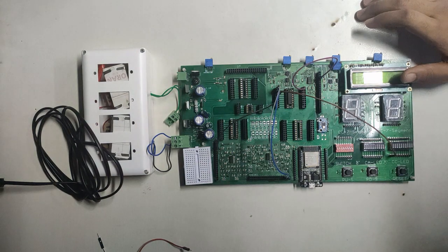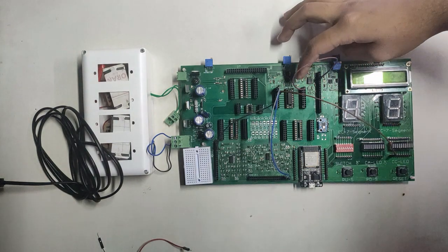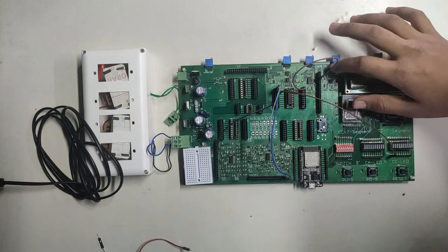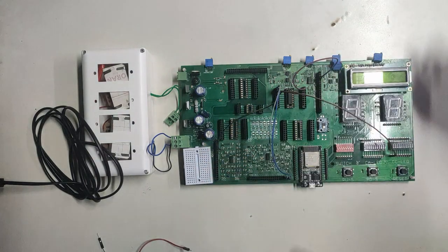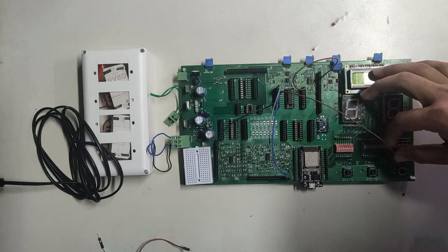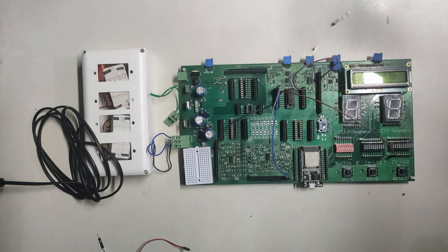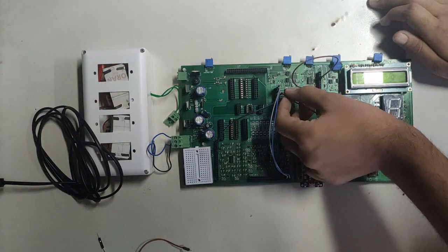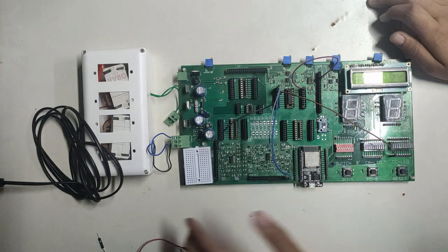After referring to the pin diagram of IC 7400, the NAND gate, you can say that pin number 14 again is the VCC, so it is connected to plus 5 volt. Pin number 7 again is ground. Now let us check the various states. Let us verify the truth table of the NAND gate. This is the first case, in which both the inputs are 0, 0. Let us check what the output is.